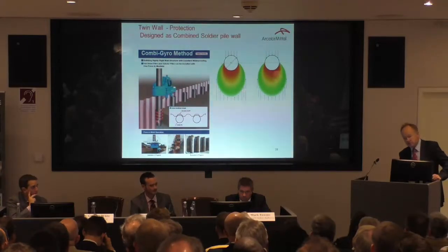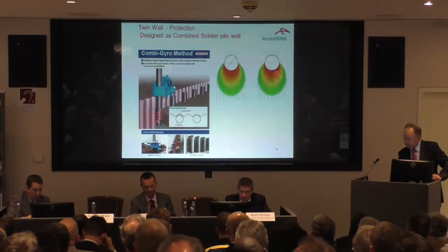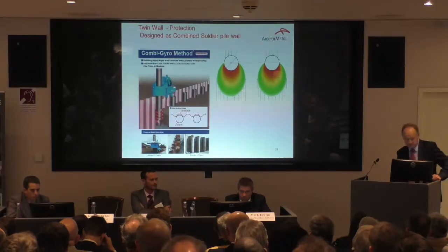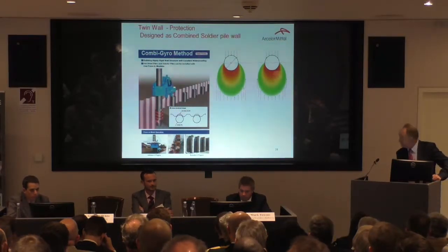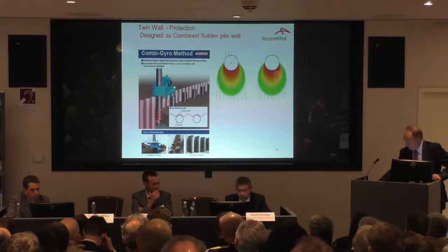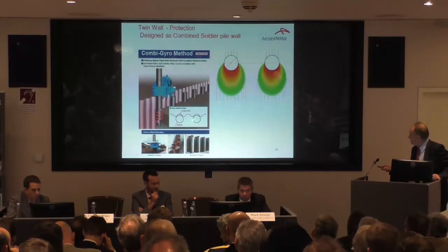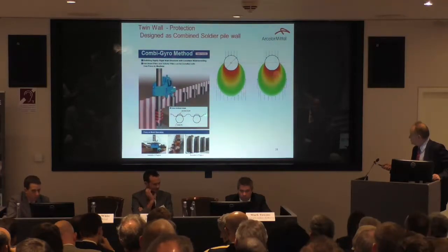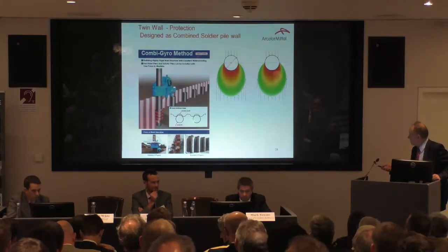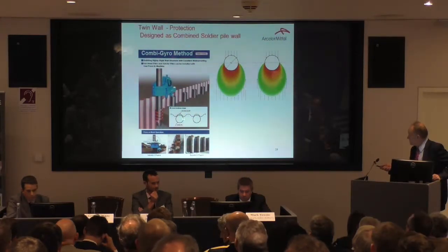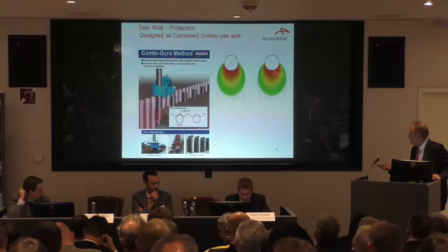One of the best ways to protect a structure using modern installation techniques is, in my opinion, using a double wall type combi wall structure. So instead of having the intermediate piles joining primary pile tubes together, you install a sheet pile wall first to so many meters below formation level, and then you have a very deep primary pile, in this case a tube, sitting at spacings usually up to 3 times the diameter.